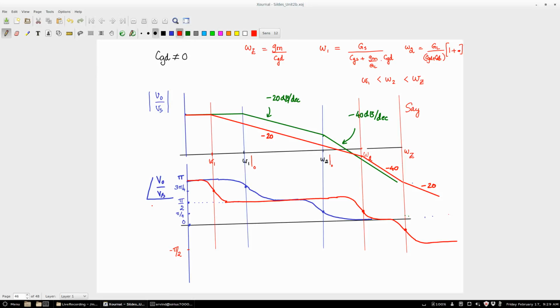Basically, all of you have experienced this when you were working in the digital circuits lab. You came across one situation where things started oscillating, right? Why? Because it was not a stable system. You started getting output at some frequency. So these kinds of things have a tendency to become unstable, and in order to understand why things become unstable, you need to be able to draw the Bode plot, both the magnitude and the phase. Okay, so we will see this.